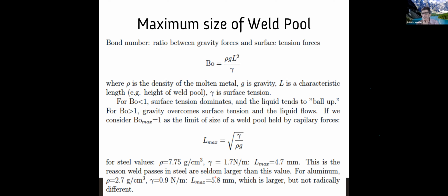Okay, interesting. So if I were to have such a huge weld, that means it would take very long to cool down. Regardless of gravity, the heat transfer doesn't care about gravity. So we might end up with a problem of coarsening. For example, we have huge welds when we do electroslag or electrogas welding. Those are huge and very productive, but we have an enormous coarsening in the heat affected zone.